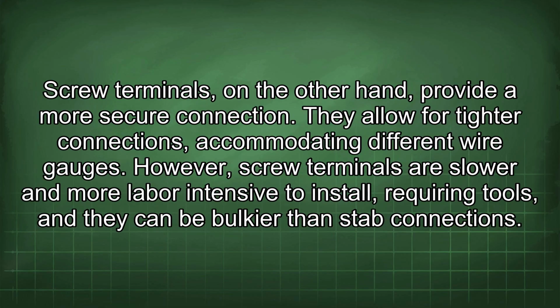Screw terminals, on the other hand, provide a more secure connection. They allow for tighter connections, accommodating different wire gauges. However, screw terminals are slower and more labor-intensive to install, requiring tools, and they can be bulkier than stab connections.